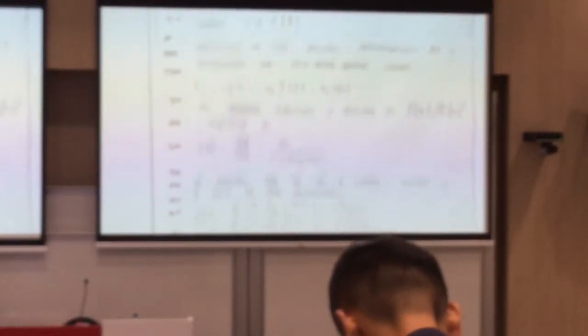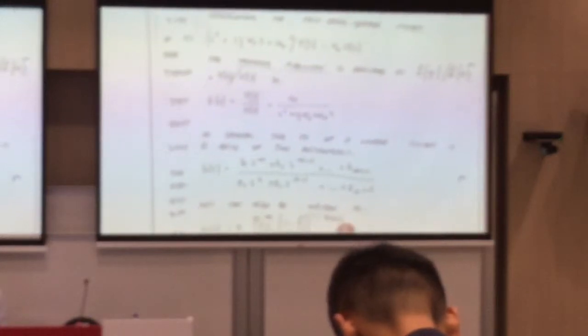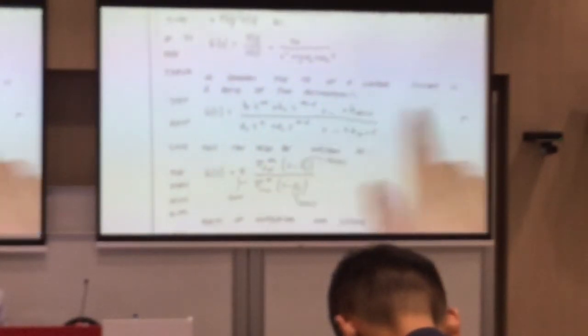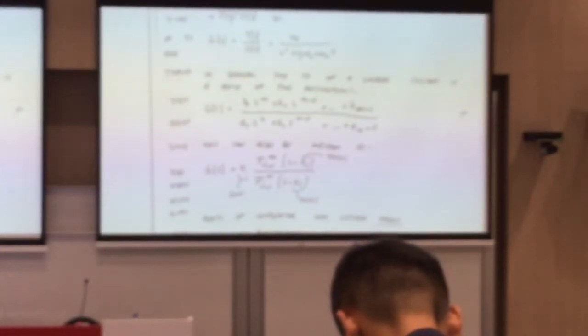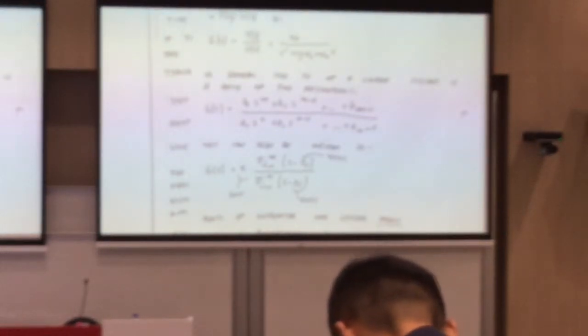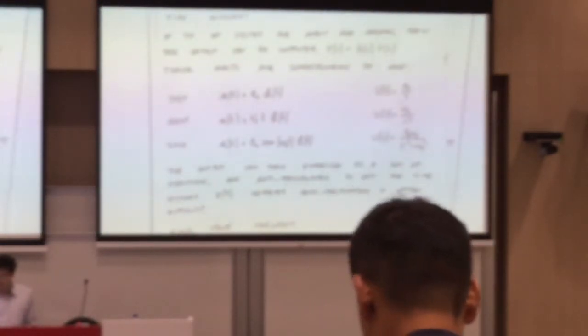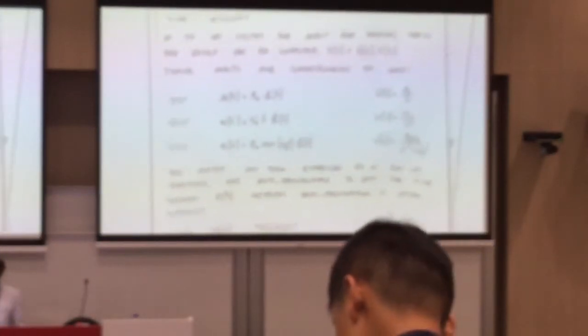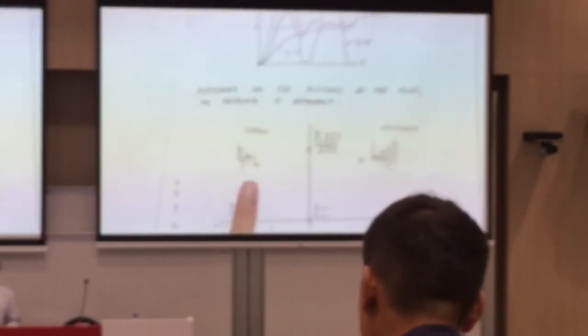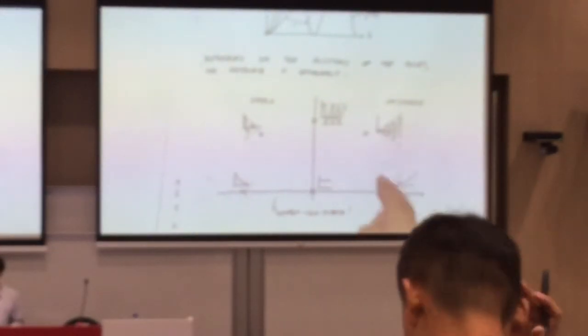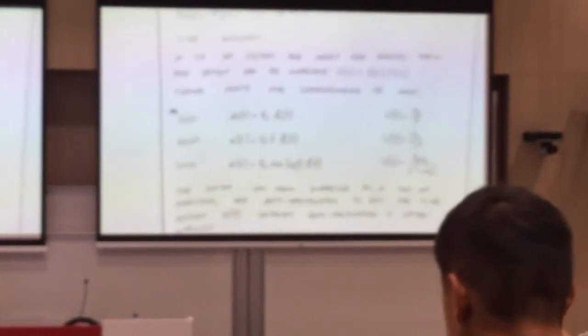And for the Laplace transform, after you get the S function, basically you have the numerator and denominator, right? And usually you will present this one after factorization. You will get the zeros and the poles. So you know the zeros, and especially the location of the poles is very important, right? This becomes your link to your system performance. The location of the poles has something to do with your transient response, something related with your state. So this is the main purpose for the Laplace transform.